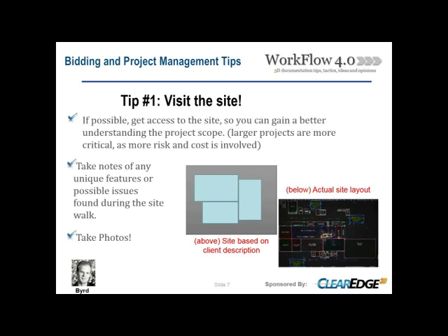So tip number one from me on bidding and project management would be to visit your site. If possible, get access, and it's going to help you better understand what it is you're getting into. And the larger the project, the more critical that step is. You know, and as you're doing your site walk, make sure to take photos and really note anything that might be unique to that site that you haven't seen before.